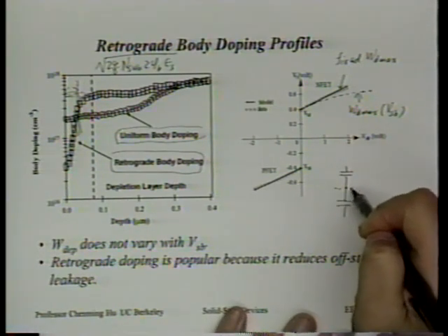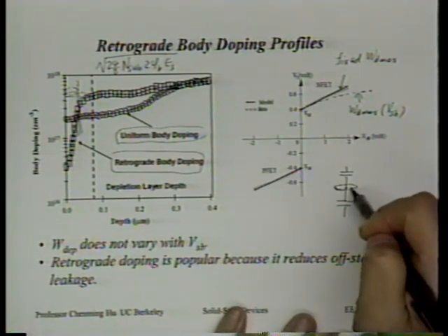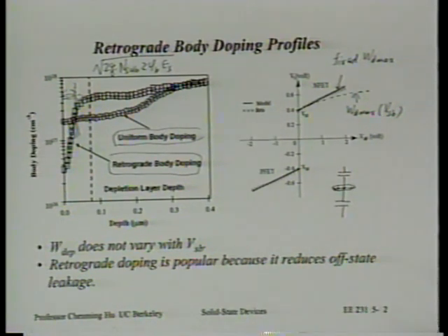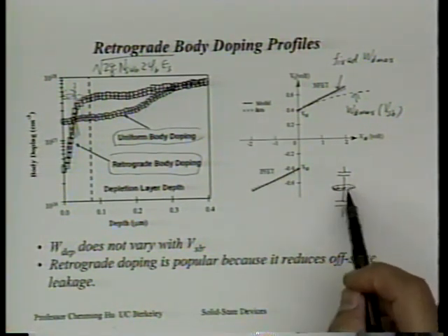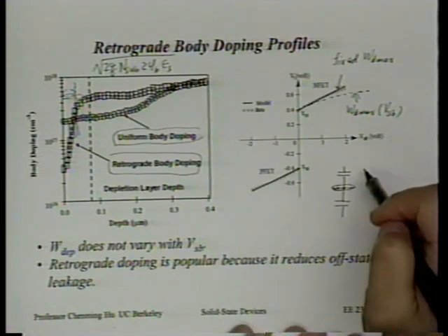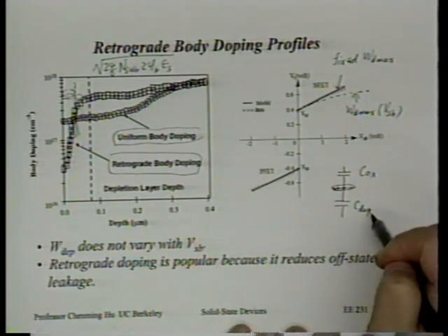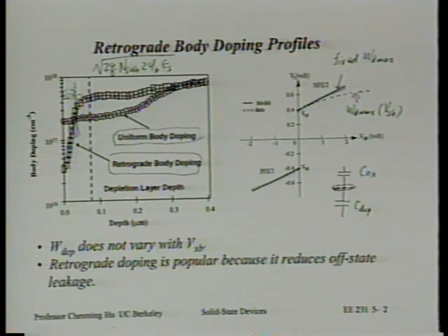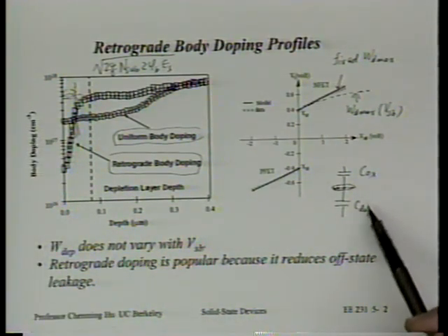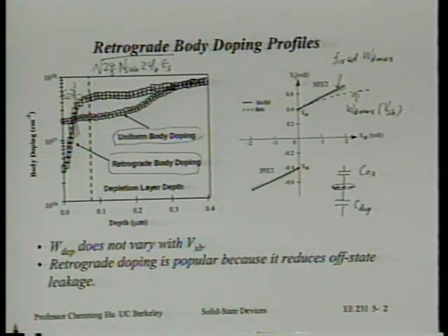This is our inversion layer, and we're interested in knowing the charge here at this inversion layer. This inversion layer is controlled by two capacitors. Cox is now a constant, and C depletion is now a constant. That's the important thing. It's not a function of body bias. As a result, there's no reason for them to have any unusual relationship. Both of these would have a linear control of the Q inversion. Is that right?